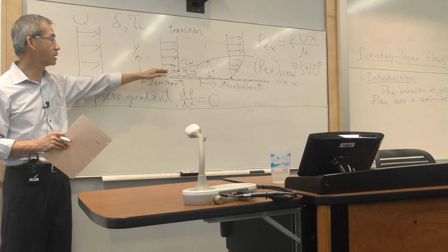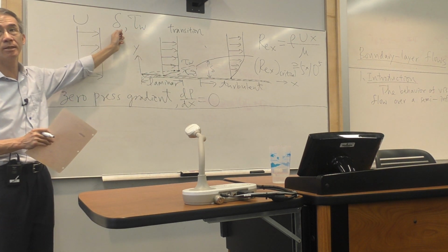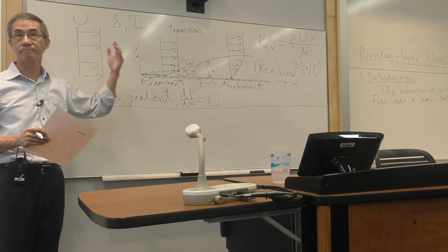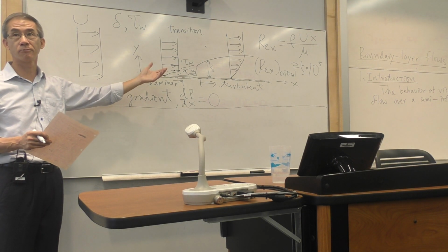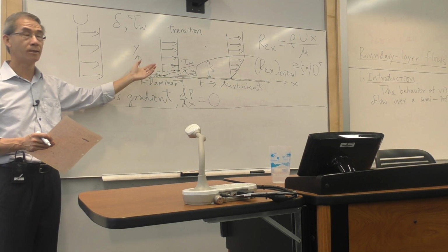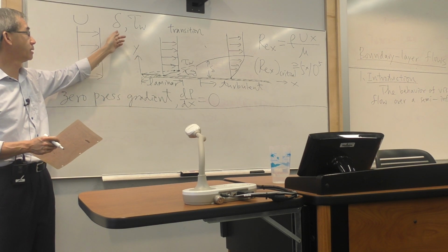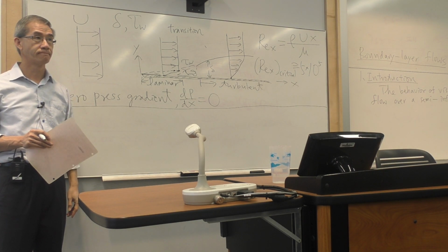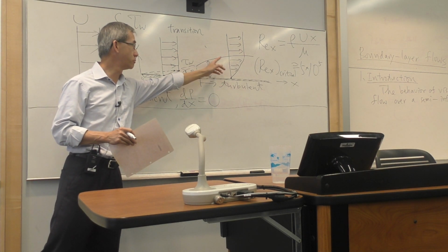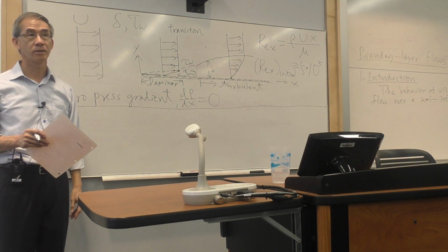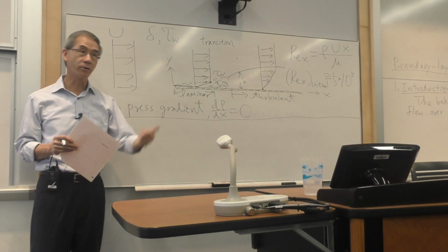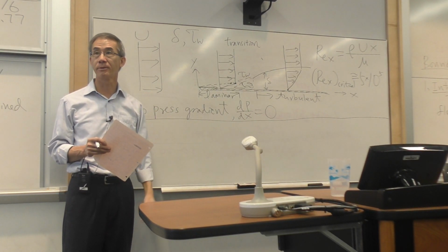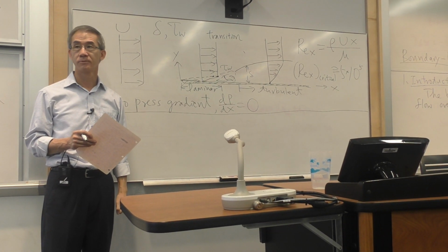Okay? It turns out to get the velocity profile or this quantity, all I need, and you can tell me, are what equations? If I give you a quiz next lecture and ask what equations you will put down to analyze this problem so that I have a hope of getting the thicknesses and the shear, what equations will you put down for me? I want to get the velocity distribution within this viscous flow. What are the equations you will put down? Continuity, without thinking. You always need continuity, and that's exactly what will happen. What else?